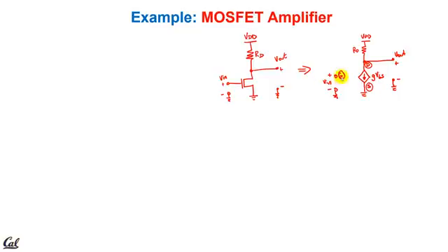Let's not think right now too much about values of stuff or what the input looks like. But if I'm in saturation, what is the value of V out? Just thinking it through, using the stuff we know. If we're in saturation, we know that IDS, this current, is a constant value. That current flows through RD, so there's a voltage drop across that resistor. This equals IDS effectively, because there's nothing that can run down this way. It's all going to run down that way.